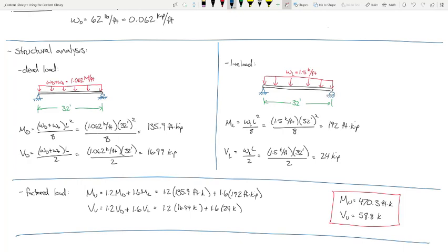So what you would have to do here is say, okay, the dead load is W_DL squared over 8, and then the live load is PL over 4, because that's the expression for maximum moment under a point load at midspan, okay? So that's why I'm saying I want you to get the habit of handling them separately, because if they are different load cases, then they are going to be separate expressions, okay? Does that make sense?